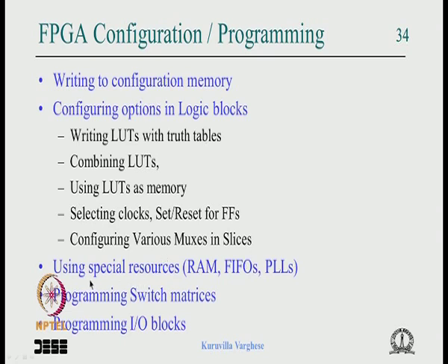In addition you can configure the memory, FIFO, PLL, all that. There could be memory blocks which are combined to make a larger width or larger depth. All that combining is done through various extra circuitry which is configured by writing to the configuration memory, and all the programming of the interconnection, and the IO blocks, there is programming available for using them as output, input, IOs and so on. So all that is done.